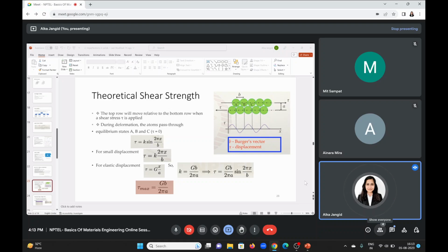what is the grain size, or what is the strain that is present from that. Or if the peaks are merging, then you can understand that there is formation of some substitutional alloy. So you can tell what type of phases are present also. If they are separately present, then there will be different peaks.